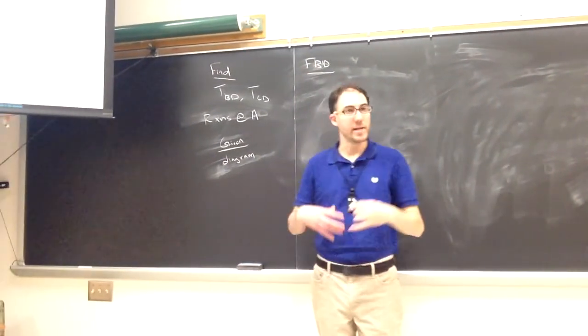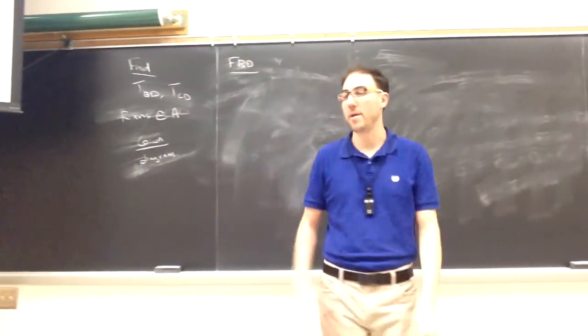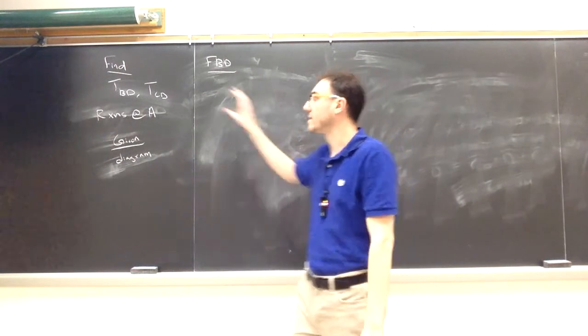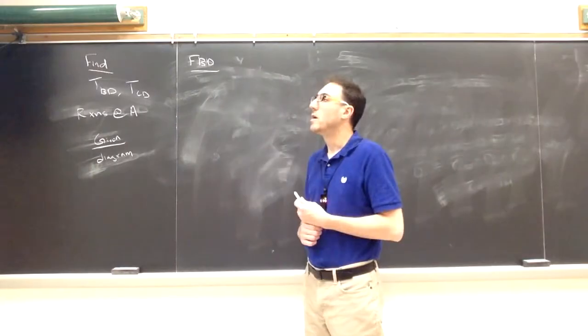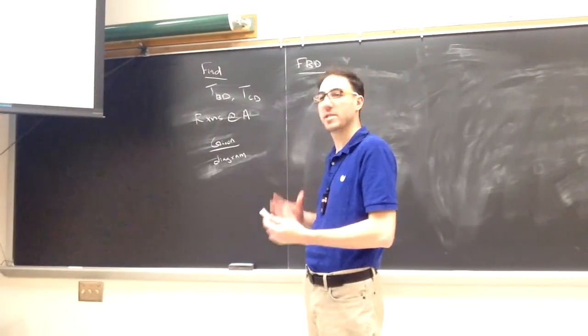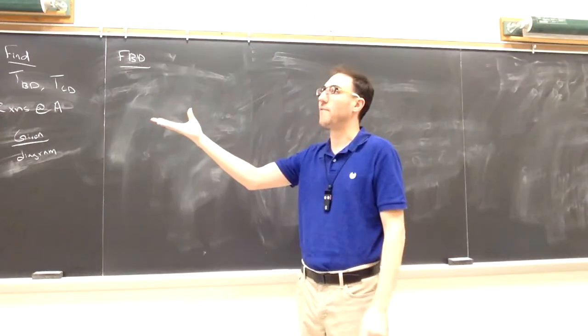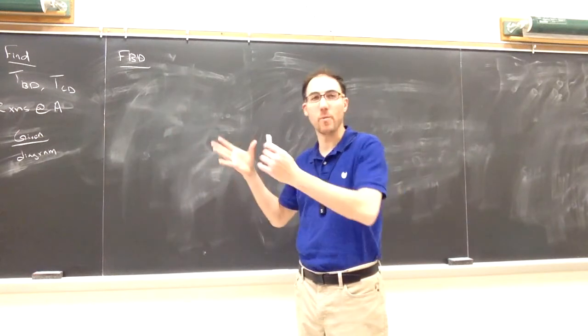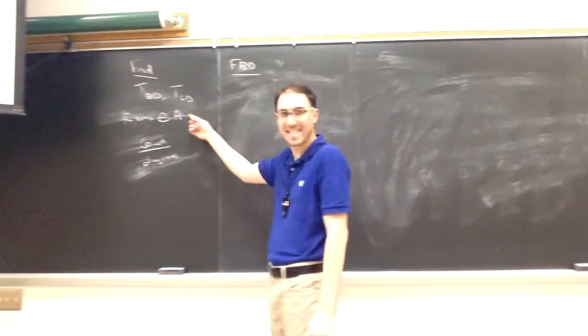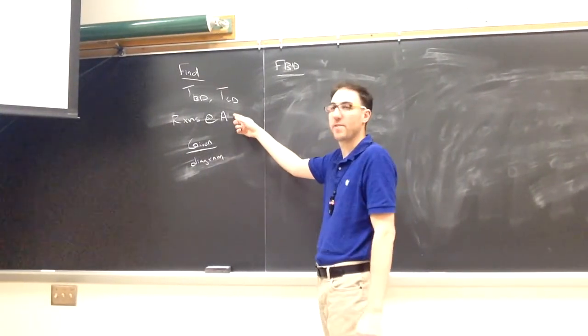So what we need to do is make the free body diagram that we're going to use to create our equations that we're then going to solve to get what we were asked to find. So what's the object that you chose to isolate from its supports, from its connections for this one? The blue platform is a good choice here, so we will disconnect it from the ball and socket connection, which means we'll be able to then see the reactions at A, whatever they may be.